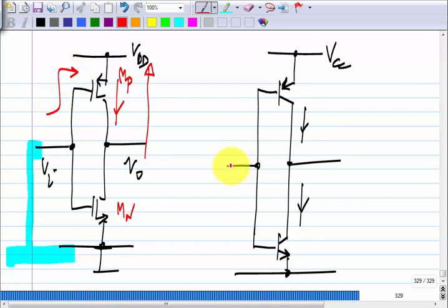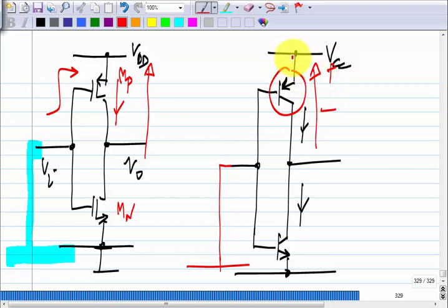If you do this with bipolar, what happens is that this will go up and this will enter the bipolar saturation region, that is a small VEC region. Once you do that, essentially this base current increases out of control. So, this is like you are applying VCC across a PN junction. You can't do that, right? The amount of voltage you can apply across a forward bias PN junction is limited, because of the exponential characteristic. If you do try to apply a larger voltage, the current will go out of control and somehow destroy the device.